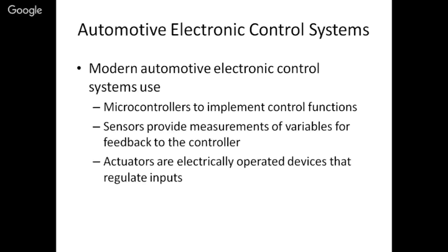So in that case, if the mixture becomes too rich, the ECU will instruct the injectors to inject a lesser amount of petrol or whatever fuel. So micro sensors with actuators and microcontrollers are fundamental to the use of MPFI or CRDI engines.